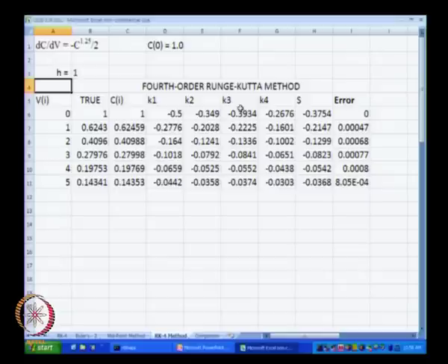This expression we obtained by deriving the design equation for a plug flow reactor. We start with an initial concentration of the reactant equal to 1, and starting with this initial concentration of 1, the concentration keeps decreasing as the volume keeps increasing.